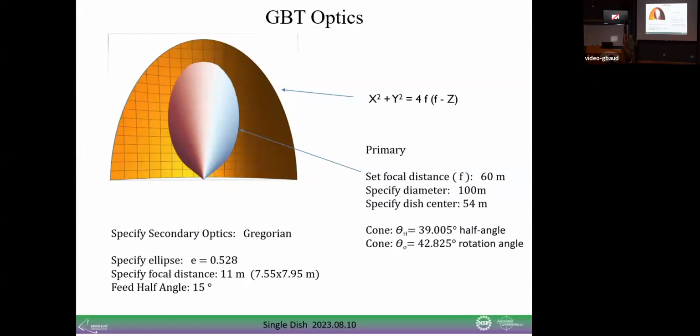In order to maximize the aperture efficiency over the system temperature, there's a certain taper, meaning the feed illumination of the dish falls off at the edge, and there's an optimum value for that that we try to achieve. I'll go over that a little bit later when I get into feed design.